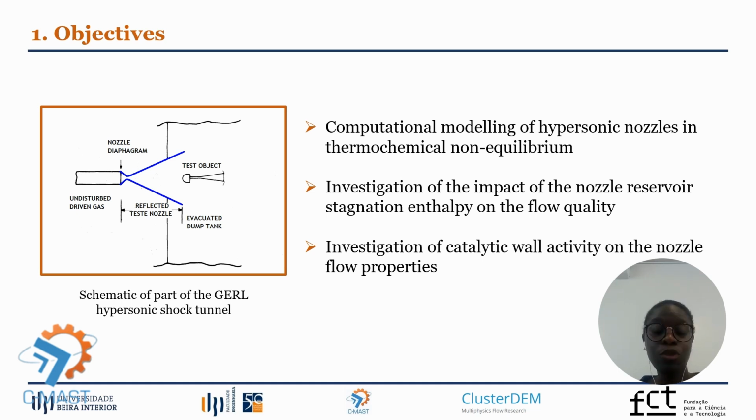This is why the computational modeling of hypersonic nozzles in thermochemical non-equilibrium is one of the objectives of this work, and also to investigate how the stagnation enthalpy at the inlet of the nozzle will change the quality of the flow. When investigating, we found that there were no studies on how the catalytic activity at the nozzle wall would influence the flow properties at the nozzle exit and test chamber. This is the reason why we investigate how the catalytic activity, that is, the reactions that occur at the nozzle surface, would impact the flow properties.